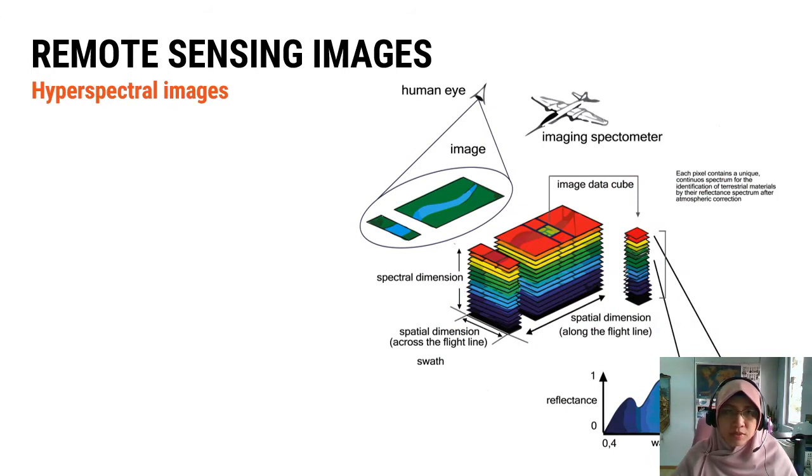Hyperspectral remote sensing combines imaging and spectroscopy in a single system, which often includes large datasets and requires new processing methods. Hyperspectral datasets are generally composed of about 100 to 200 spectral bands of relatively narrow bandwidth, 5 to 10 nanometers, whereas multispectral datasets are usually composed of about 5 to 10 bands of relatively large bandwidth, 70 to 400 nanometers.